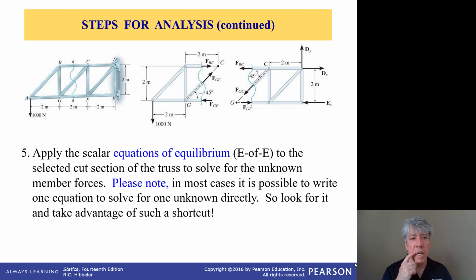Finally, once we've got it all set up, then we can apply the scalar equations of equilibrium. Now notice that there are going to be three equations. There's going to be a sum of force in x, sum of force in y, and a moment equation that will allow you to calculate all three of the unknown loads, which would be the maximum number you could accommodate. Now, there are often shortcuts for calculating things.